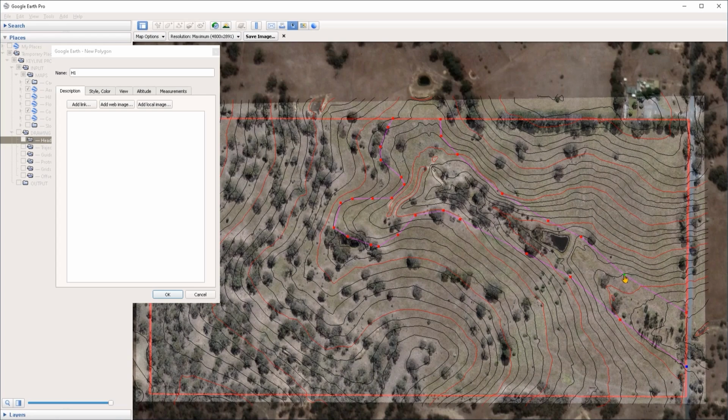You can just left click, hold and drag on any of these points on this geometry in order to move them around. If you want to delete a certain point, you can again just left click on it to highlight it, and you can press the right mouse button or just press the delete button on your keyboard. So for instance, I'm going to think, well, do I really need this point here? Because later I'll have to struggle to create an offset that takes into account that there is a break in the line here. So in this case, I'm going to left click on it to highlight it, and I'm just going to right click with my mouse to remove it.